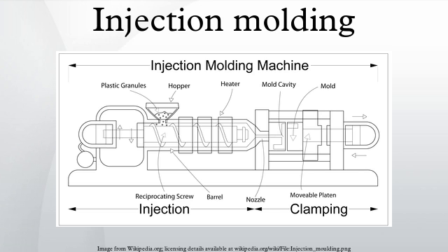Process characteristics: injection molding utilizes a ram or screw-type plunger to force molten plastic material into a mold cavity. This solidifies into a shape that is conformed to the contour of the mold. It is most commonly used to process both thermoplastic and thermosetting polymers, with the former being considerably more prolific in terms of annual material volumes processed.